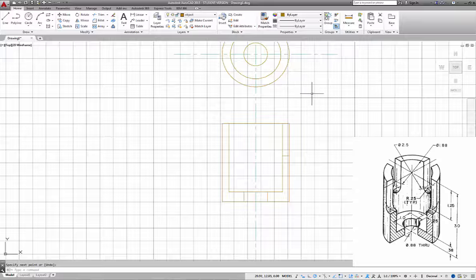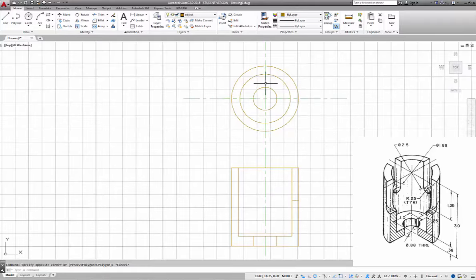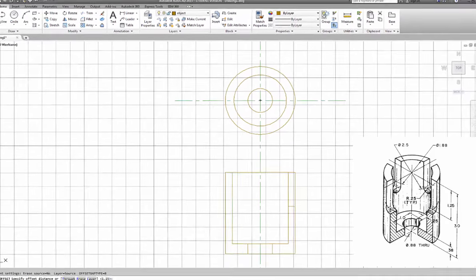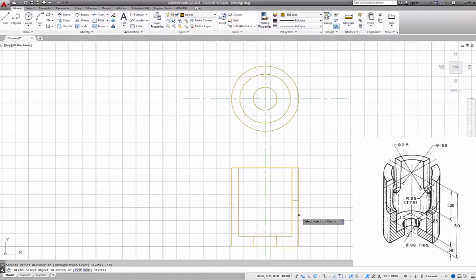Now, there is a keyway in this object. So this keyway happens to be 1 inch total distance from one end to the other, and it's a 1/4 inch wide. And oh, I made a mistake. This is supposed to be 3/8 and not 1/4. So let's go ahead and offset 0.375. We'll clean this up here really quick. This offsets in, this offsets in. I'll delete this line here, and things don't always go as planned. So we'll fix the corners here.